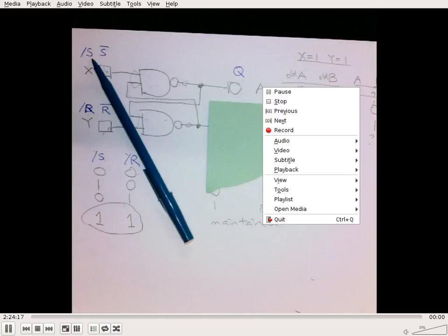So the brownout detection circuit is basically setting a threshold and saying if the regulated voltage from your power supply drops below a certain point, it is considered bad. Just reset everything. Hold the reset line so that nothing works. They basically all stop. But when they all stop, it is a quote-unquote safe state because nothing is being done. You're not continuing to write anything to the SATA drive, which is probably a better thing than spewing out some random data to some random sector on your hard drive.